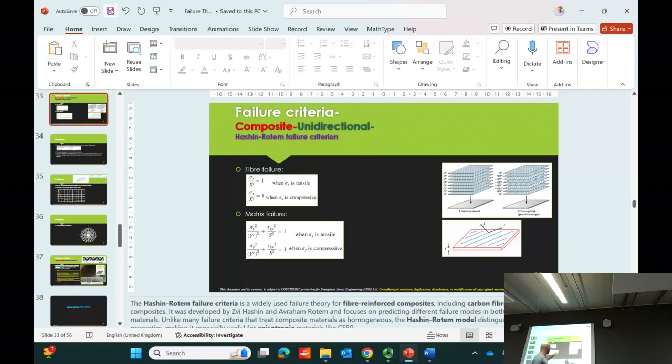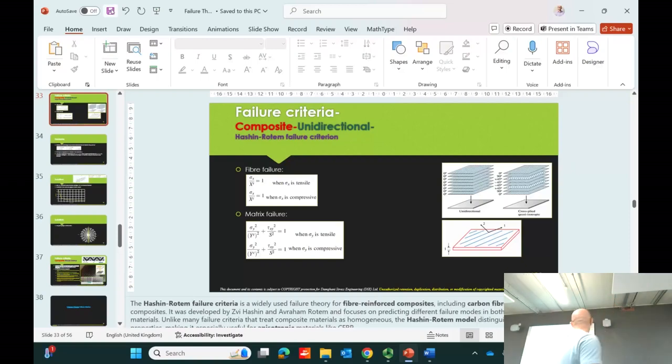Okay? And this is mostly predominant where you have shearing of your material. If you've got axial loading, tensile and compressive, it's not that precise. Hence, it's always used in combination with another failure criteria which is good for tensile and compressive and all that direct loading, and can give you a good fiber failure. Yeah, that's why it's just being used with the matrix.